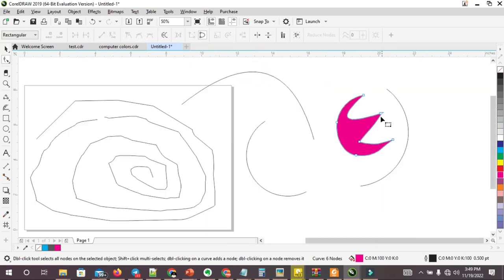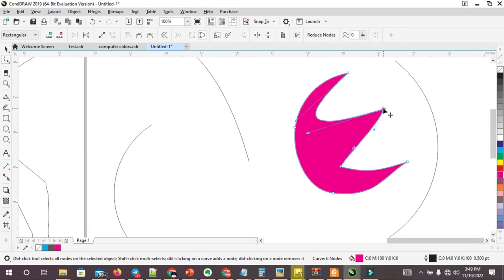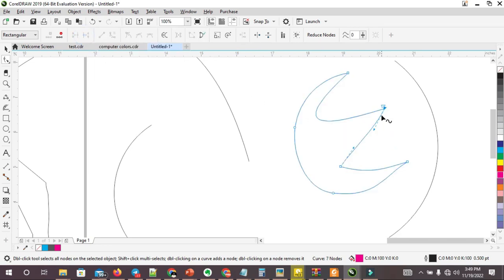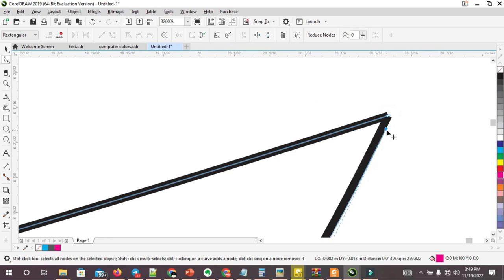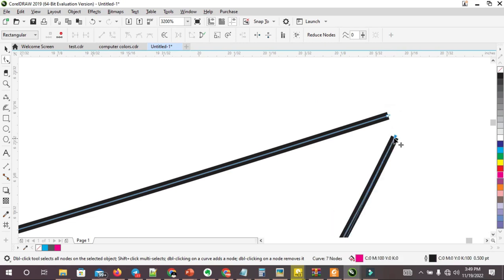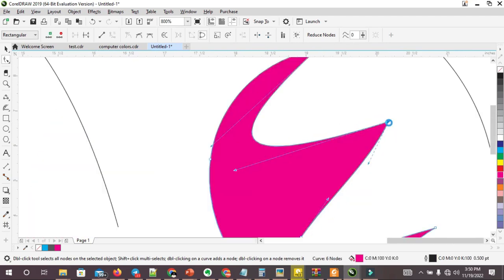And the way to achieve the shape is to make sure that your lines meet. Create lines that have a closed node. This is an open node. If I open it now, the shape is going to disappear. But once it's closed, how you close it is when you take this blue, which is like a fill, and you drop it on this until you see the icon. That is when you achieve a shape.